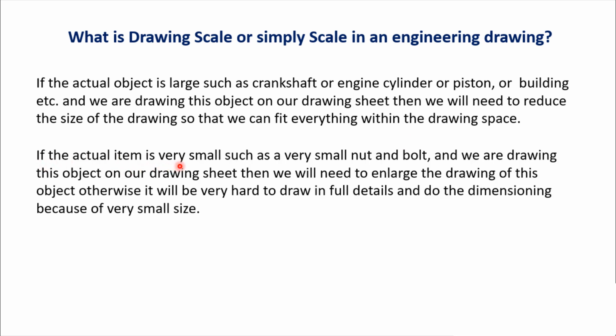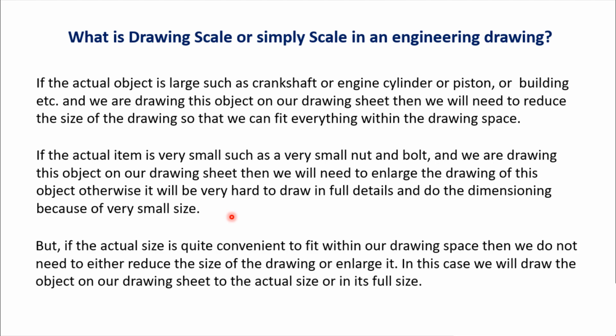If the actual item is very small, such as very small nut and bolt, and we are drawing this object on our drawing sheet, then we will need to enlarge the drawing of this object. Otherwise, it will be very hard to draw in full details and do the dimensioning because of very small size. But if the actual size is quite convenient to fit within our drawing space, then we do not need to either reduce the size of the drawing or enlarge it.